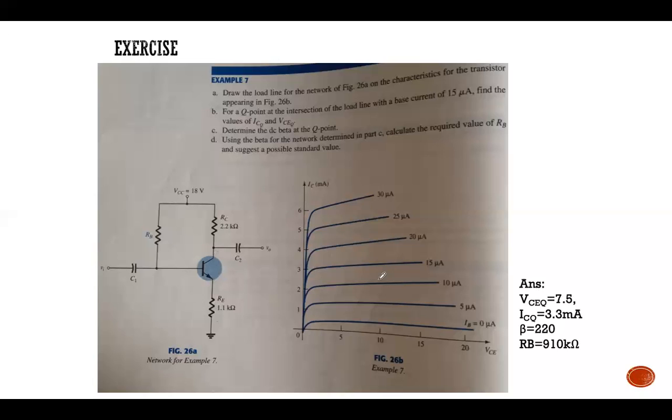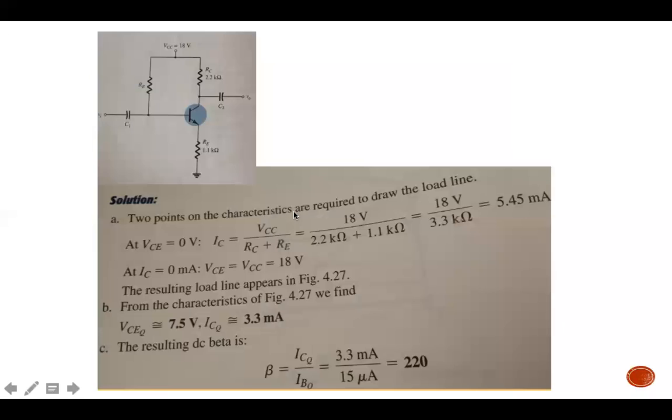So how to draw the load line? You need to calculate the intersection for the VCE and also the IC saturation. If you remember, you can directly use the formula, so you don't need to derive.